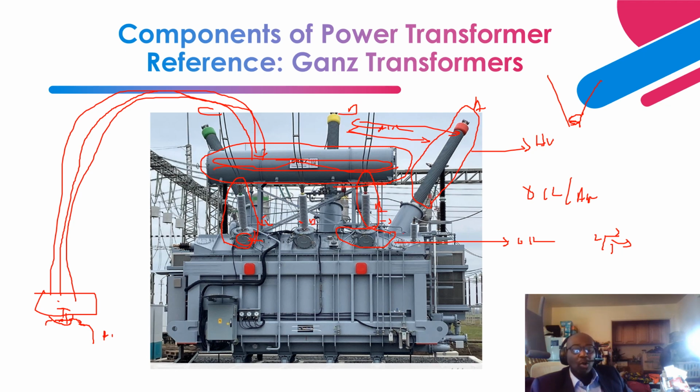Okay, so the high voltage side, similarly, these are the turrets. Inside the turret is filled with oil and has CTs, about 3 of them. Let's say utilizing one for metering, one for protection, and the other one as a spare. On this side is the surge arrestor, and I explained to you what a surge arrestor does. It basically protects the transformer from overvoltage conditions, from lightning impulse strikes and switching impulse strikes.